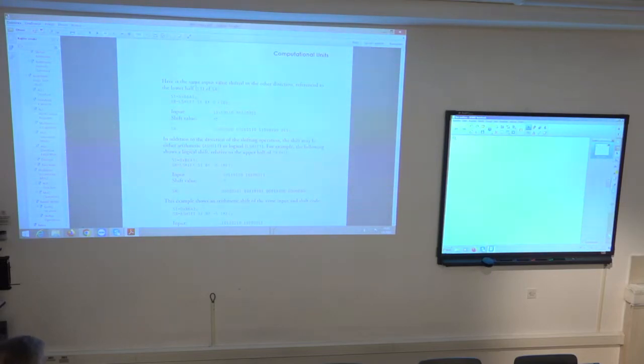Then we have another example. Logical shift of SI by -5, in this case relatively high. You place the value in the upper register and then shift it 5 positions. So you see this 1, 0, 1, 1. I have 5 zeros and then 1, 0, 1, 0, 1, 1.